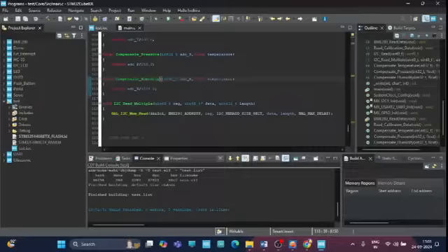And now let me show you the output. I have already recorded the output video. You just need to connect your BME280 sensor with your STM32 board, ground to ground, VCC to 5 volt, and the clock and data pins are already present in the STM32, right? So connect the clock to the clock pin and data to the data pin.